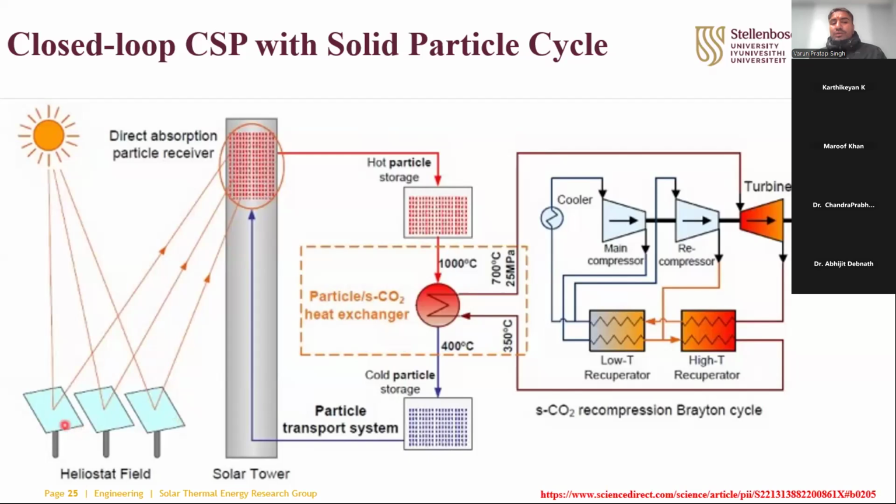I mentioned 40,000 to 70,000 heliostats, each 25-meter square, which are going to focus over there. So obviously you need a central sphere placed at quite a high height to make them more efficient. For 30 years, I am planning to lift my particles or thermal fluid up to 100-meter height. You can imagine the pump work input over there for 30 years.